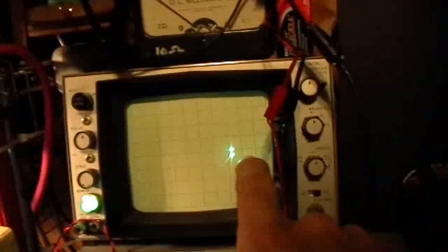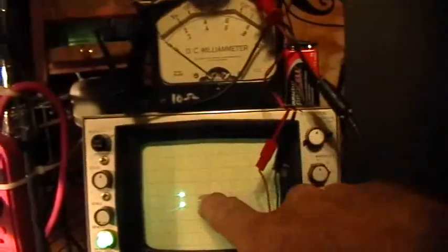Its output right here is going over to the oscilloscope, and what's being shown there is this trace going up and down, the signal from the function generator. The other dot just going across the middle is just a marker, so that you know where the middle is. It's not doing anything except indicating where the middle of that trace is. So the up and down trace there is the slow sine wave coming from the function generator, and I think you can see that it has to go a little bit positive above the tracer dot before the blue LED comes on, and then there's current flow, right?